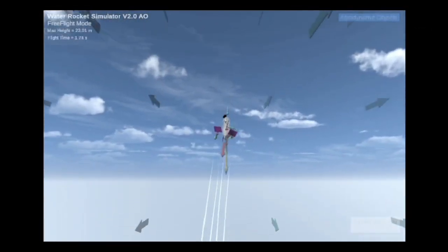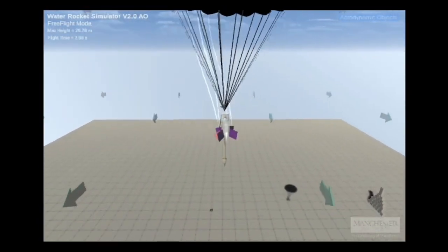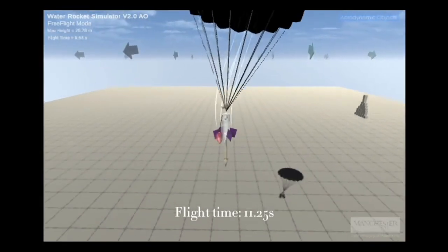However, if acceleration and the polar moment of inertia is adequately large enough, the rocket will be less affected by the crosswind. In that respect, the team made it a priority to ensure the initial thrust of the rocket was high enough to cause a large enough acceleration to combat the crosswind.